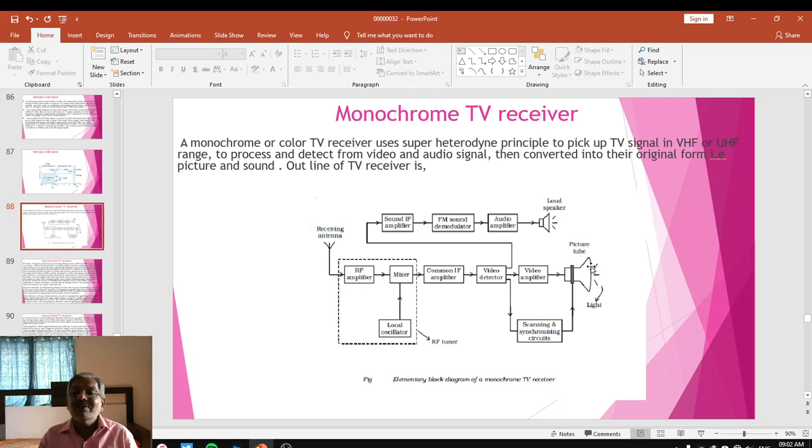Simultaneously, the horizontal and vertical deflection system starts scanning the spot from left to right of the screen horizontally and from top to bottom vertically, where 625 lines are scanned to form one vertical frame that carries two fields.